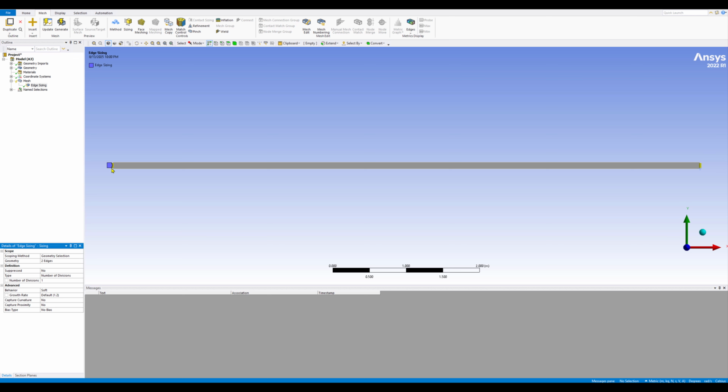of divisions, so you can specify the number of mesh in this selected surfaces. So I will change it to 5 number of divisions. You can also select this box here if you want to work a parametric and grid study for your generated mesh. You can see the first video of conduction. So in this video, I'm not going to use this parametric analysis. So I just select these 5.